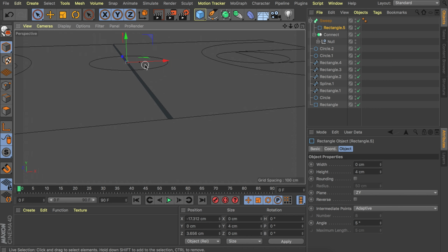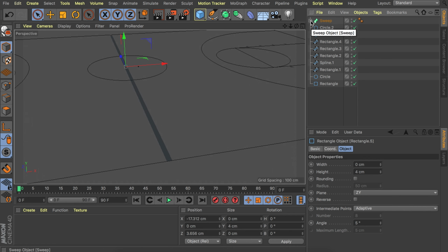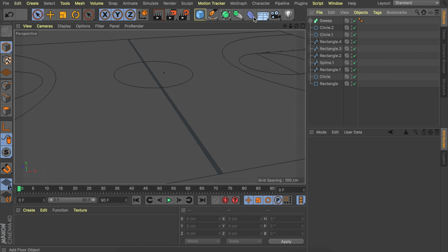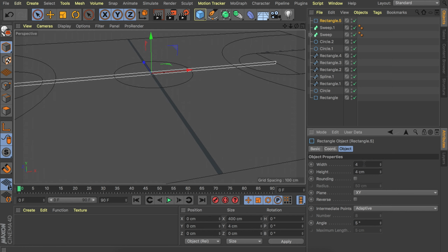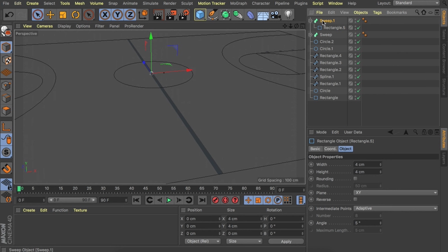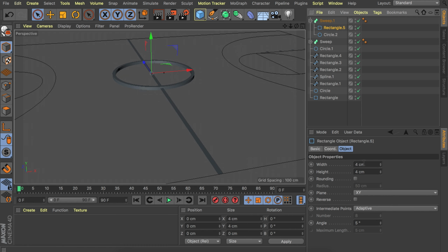We don't need that. Now we can turn all the remaining splines into sweeps in a similar way, but they unfortunately need to be done individually to avoid glitches and gaps. I'm not sure why it happens. So once you've set up the first sweep and got the rectangle's orientation right, you can just copy that one and work your way through the list.